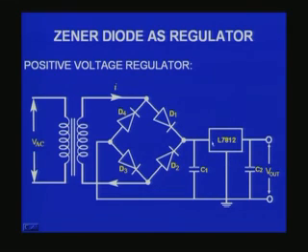What is the circuit that we have here? It actually contains the different circuits that I just mentioned. You have an internal regulated power supply with a Zener regulator, a pass transistor and a current limiting device, all built in integrated circuit form. And therefore, if I give the input here and take the output here, the output will be a constant value. The value of the constant is given by the last 2 digits of this IC number.